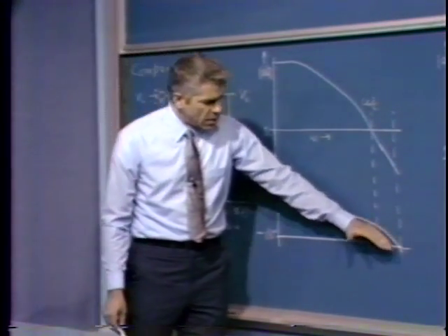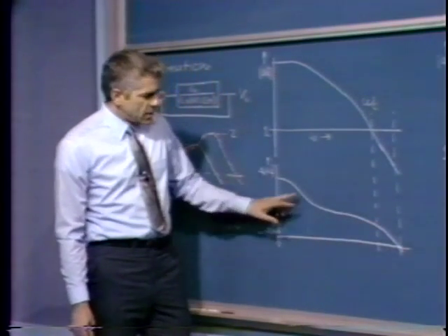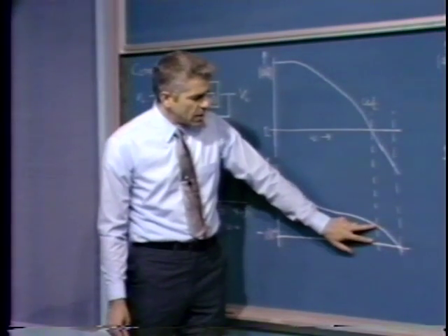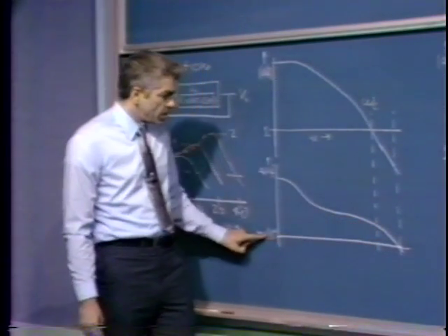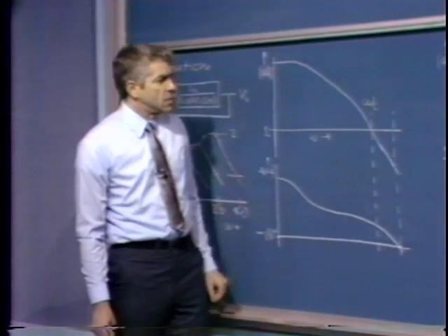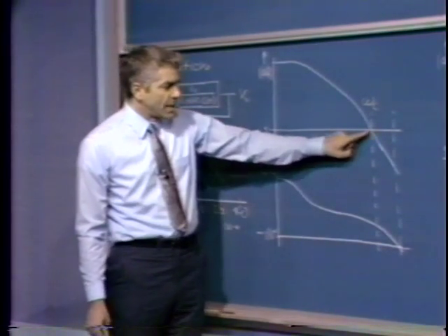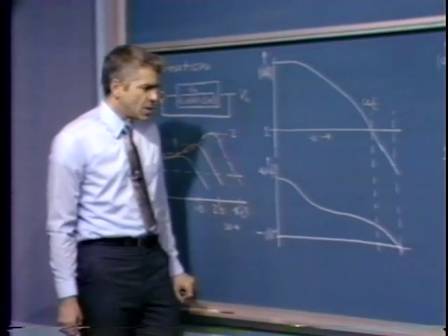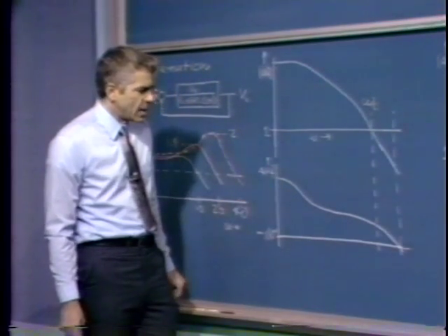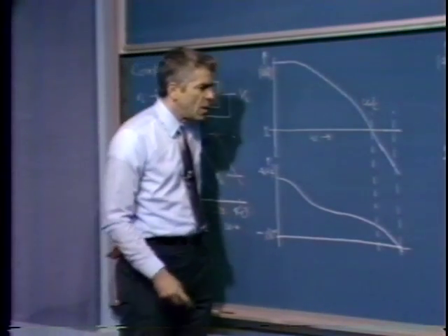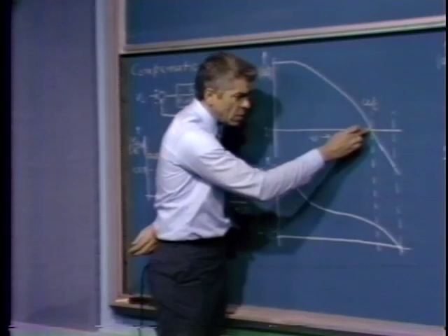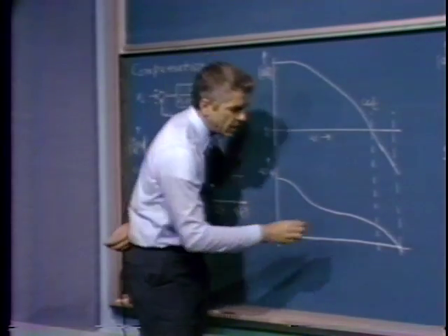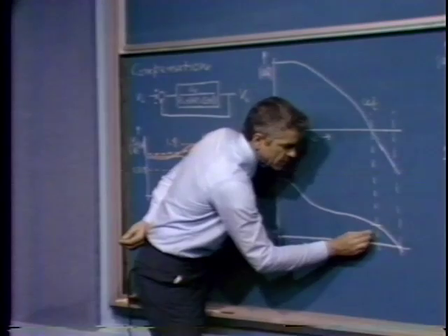If we have this sort of well-behaved system, then in fact the Nyquist test simplifies greatly, and we can convince ourselves that, providing the angle has not yet reached minus 180 degrees when the magnitude has gotten down to 1, the system will be stable. And so here we've shown that situation. The magnitude of the AF product is 1. The angle is somewhat more positive than minus 180 degrees. And for this sort of simple, well-behaved system, that guarantees stability if we conducted the Nyquist test. Once we've convinced ourselves the system is stable, we can look at the crossover frequency. In other words, look at the frequency where the magnitude of the AF product is 1, and this distance is the phase margin.